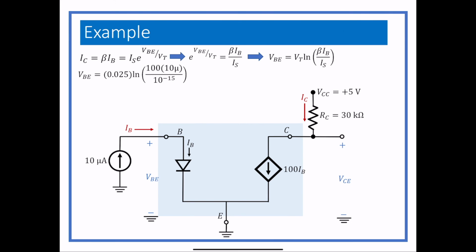So we go through and we get 0.025 for the thermal voltage. Remember that usually we use 25 millivolts in here, mainly because room temperature is actually lower than 300K. So if you use 25 or 26, I don't really care. You'll come up with different numbers if you use 26 than 25, but not much. So we end up taking those values and we get 0.691 volts, which is similar to 0.7, which is what you would expect to get from a forward bias PN junction.